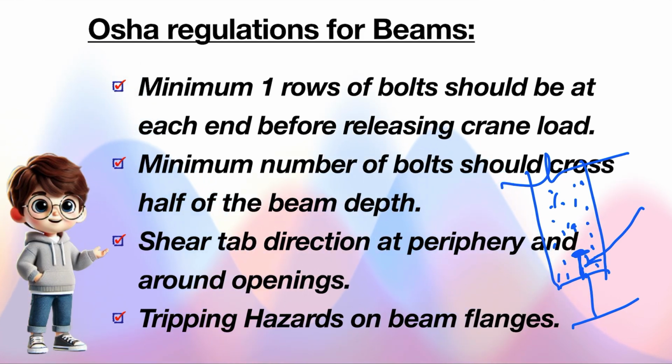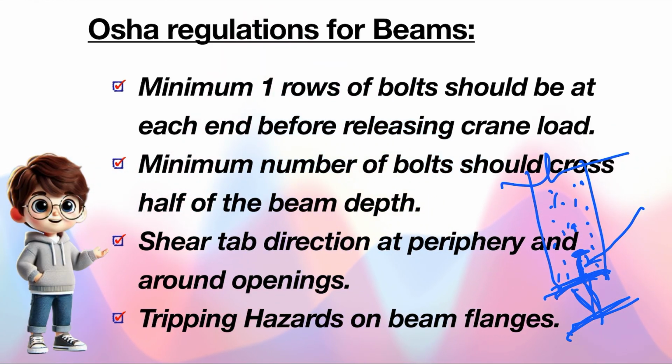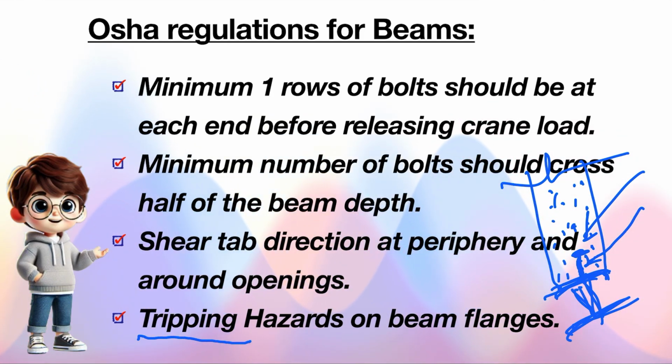In this condition we should avoid welding these studs in the shop, because the erectors who do bolt installation and erection of the beam, guiding the crane operator and all, will be working on these framing beams only. So we need to avoid shop welding anything on the beam flange, because if anything is shop welded and they are working on that beam, they may trip. If we weld anything on the beam top flange in shop, it may lead to tripping hazards at site.